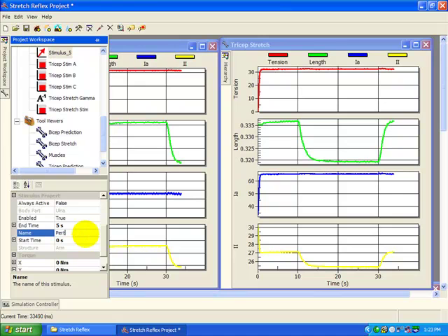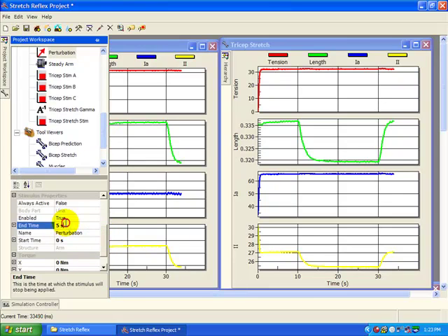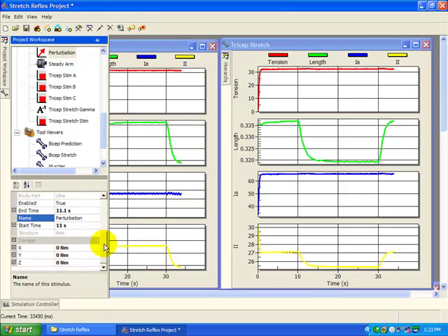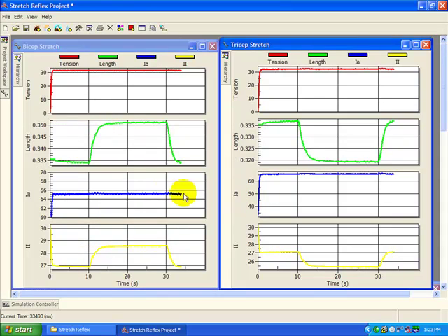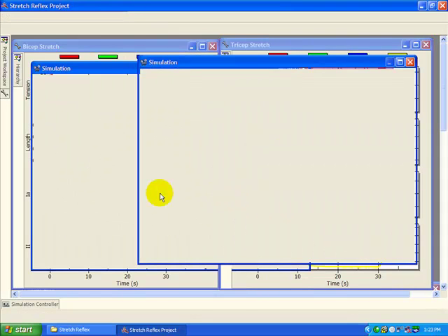Name it perturbation. Set its end time to 11.1 seconds and start time to 11 seconds. Then add a torque around the x-axis of 0.2. Then run the simulation.